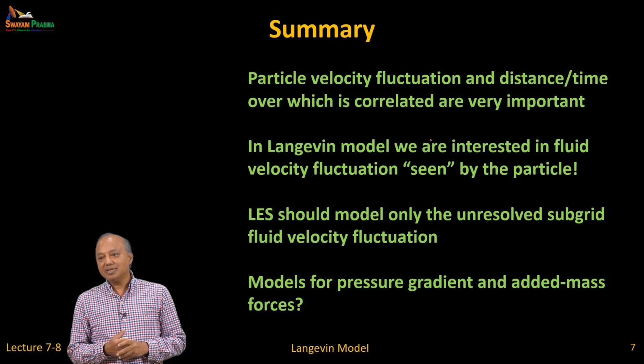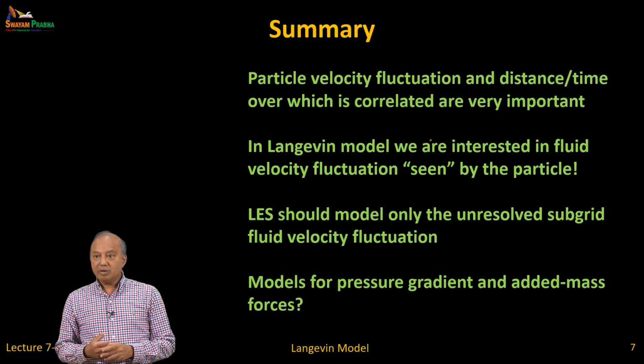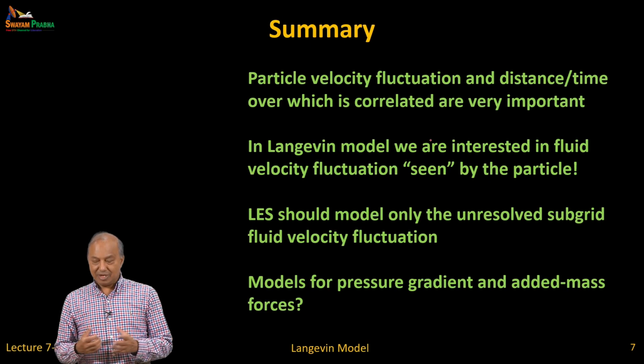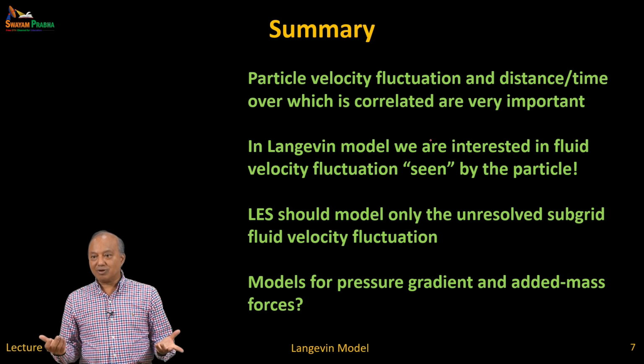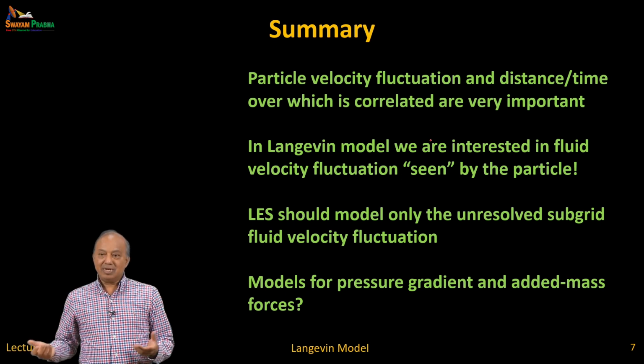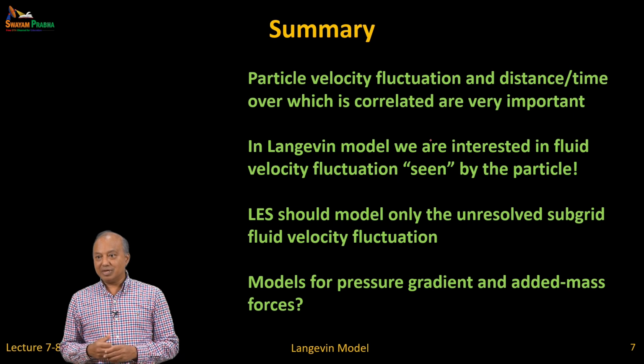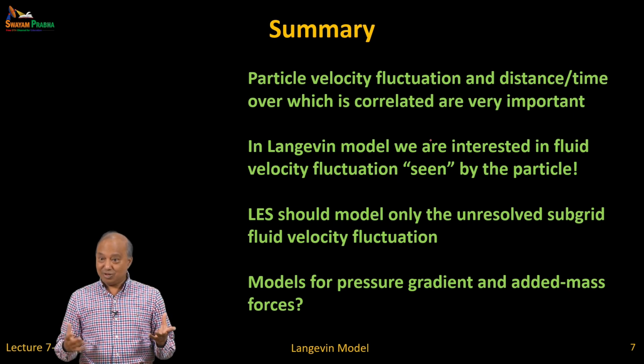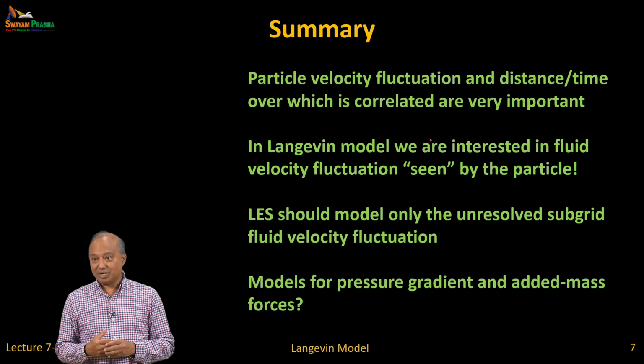Yes? Regarding the computational expensiveness, DNS is highly computationally expensive compared to the other two. So what about RANS and LES, which will be more computationally expensive? LES will be a lot more expensive, because in RANS for a stationary problem, you calculate the steady state. But in LES, since you are computing the dynamics of big eddies, you got to do a time dependent simulation.